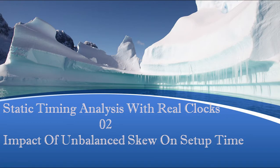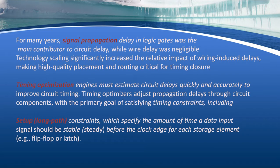Now, static timing analysis with real clock. Second, we will discuss the impact of unbalanced skew on setup timing. Signal propagation delay in logic gates was the main contributor to signal delay. While wire delay was negligible, technology scaling significantly increased the relative impact of wiring induced delays, making high quality placement and routing critical for timing.